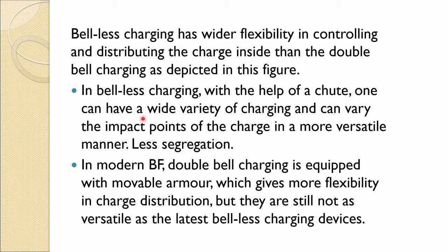There are many things in fact in the charging which one has to consider. Mostly at the impact point you will find fine deposition comes, we will show that. So, in modern blast furnaces double bell charging is equipped with movable armor which gives more flexibility in charge distribution, but they are still not as versatile as the latest bell-less charging devices.